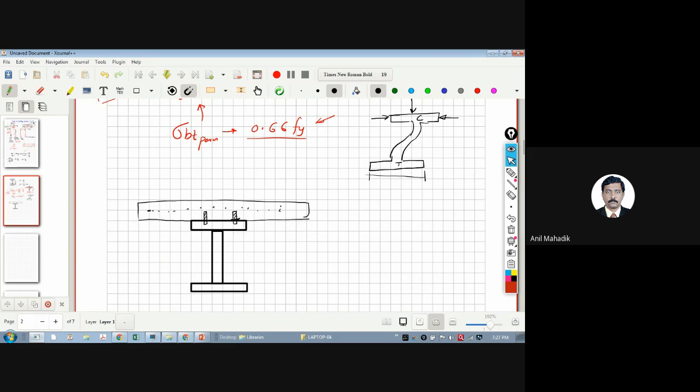I will weld this to this member and then anchor this into the slab. Now, if there is a vertical load, will it buckle in this direction? This slab will give the support to this. That means it will not buckle. So we generally call this as restrained, it is restrained in the lateral direction.